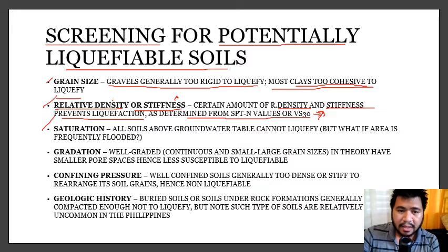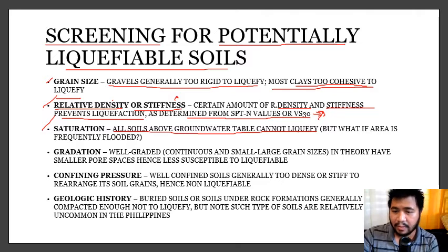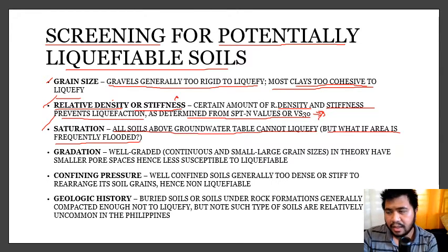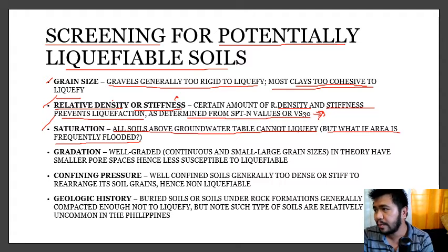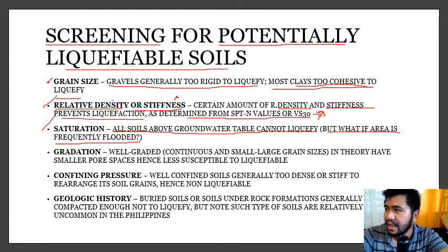Saturation: basically all the soils that are above the groundwater table cannot liquefy. If the soil is above the water table, then the soil is probably dry, so it cannot liquefy. Now, what if the soil is actually frequently flooded? Let's say you did drilling during a dry season, and this is very common in geotechnical investigations. It's better to do drilling during a dry season where the weather is favorable.